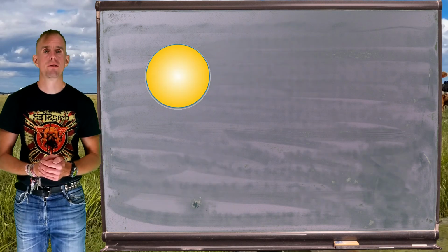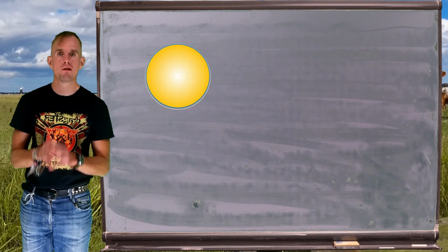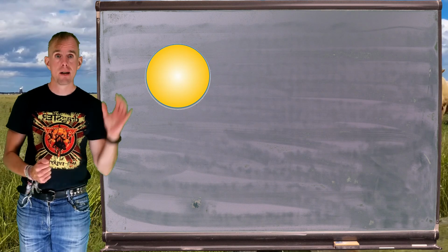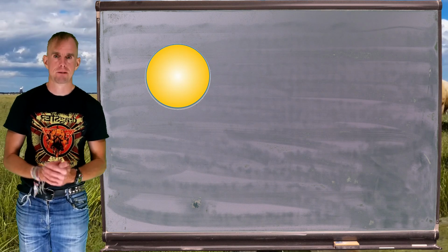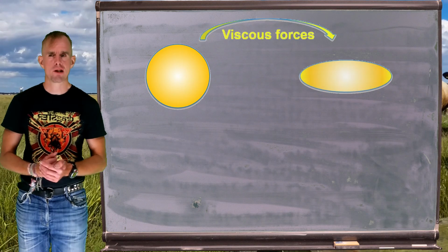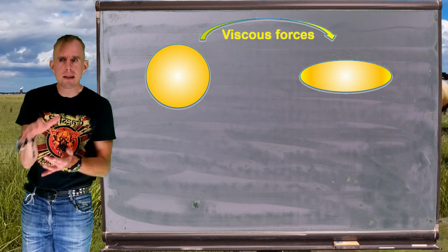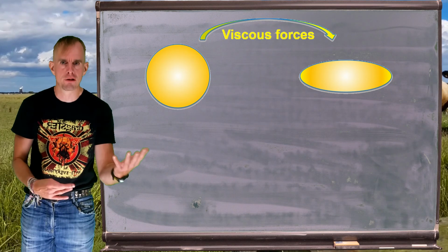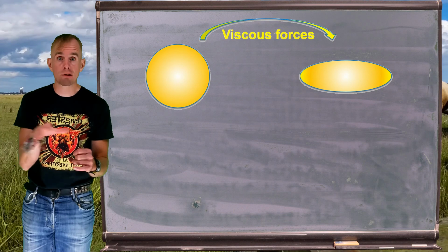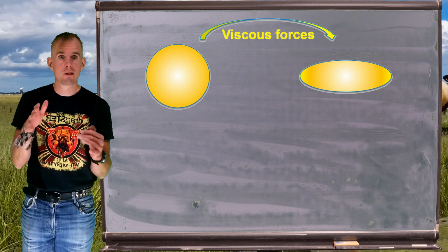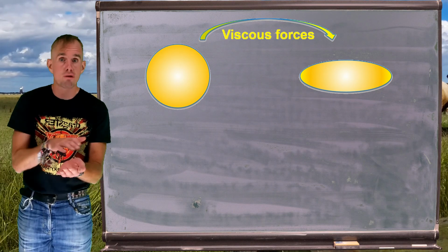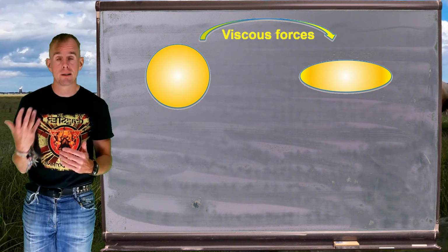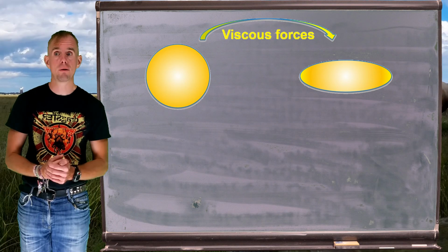We're going to focus on shear fields, and we're going to introduce a very important definition that applies to both shear and extension. Imagine a spherical droplet. Under the action of a deformation, viscous forces are placed on this droplet. Imagine that tau equals eta gamma dot. Gamma dot is our rate of deformation. Eta is the viscosity of the continuous phase. So the continuous phase exerts a viscous stress on the dispersed phase and causes it to change shape. And our initially spherical droplet becomes ellipsoidal.